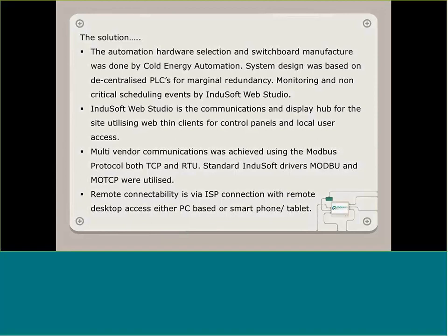The multiple vendor communications was achieved using both Modbus RTU and TCP protocols again. We used the standard libraries from Indusoft. They worked great. The remote PC and smartphone access was again just through remote desktop. Worked fantastic. Really gave us an avenue to do modifications and also further development on the site.